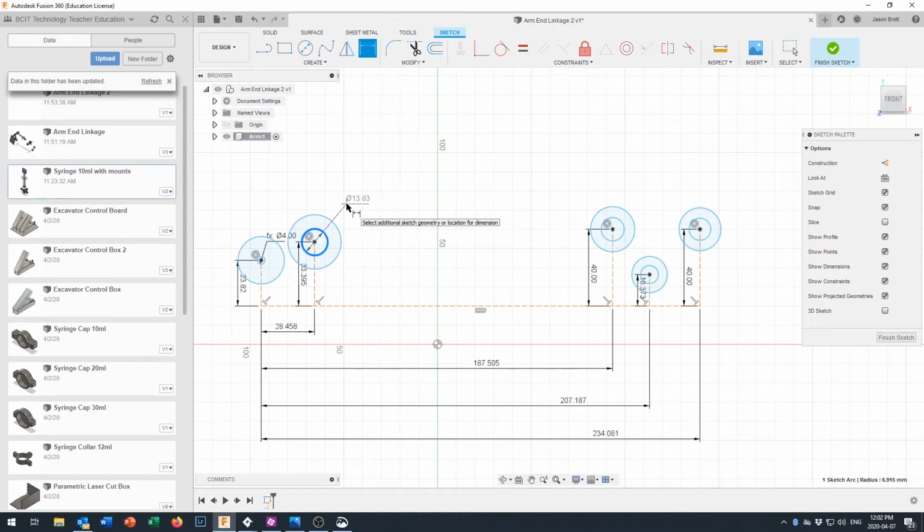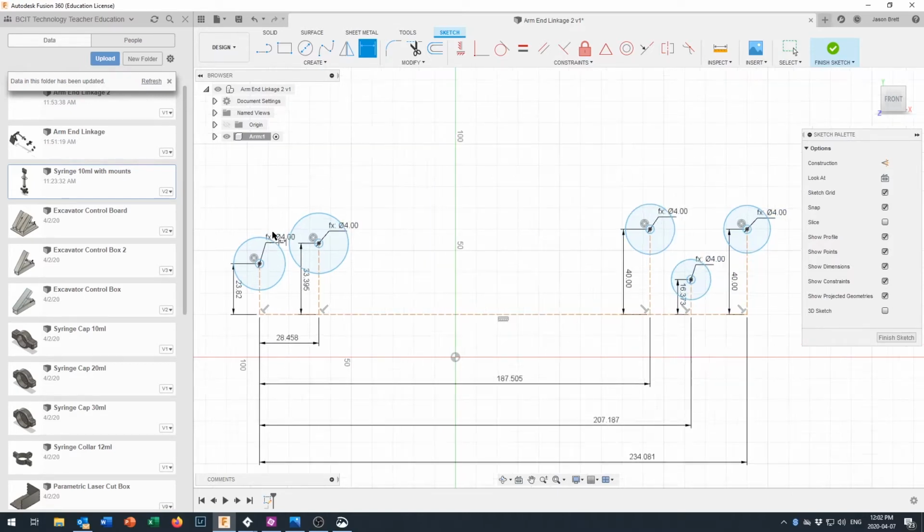And seeing as how we're going to use the same screws everywhere, I don't have to keep retyping that. I can just come back and type that in, or I can type in hole inside diameter. It really doesn't matter which you do, it's probably just as quick, and it all refers back to the same thing. Just make sure that whatever you get, they're all coming out at the right size for a number 6 screw. Okay, everybody says 4 right in there.